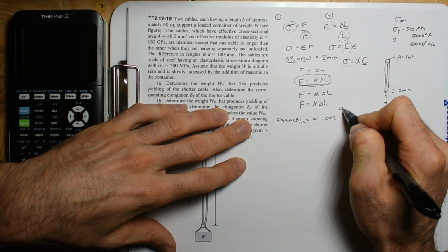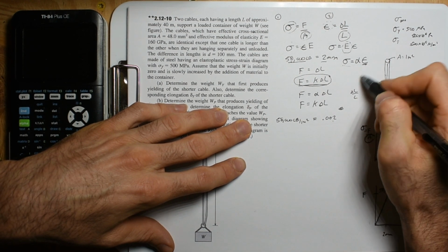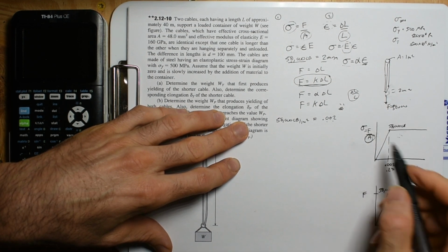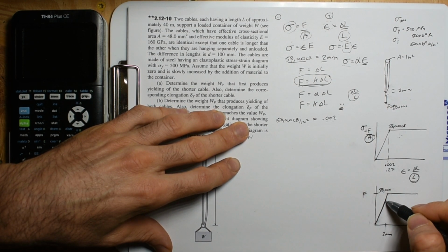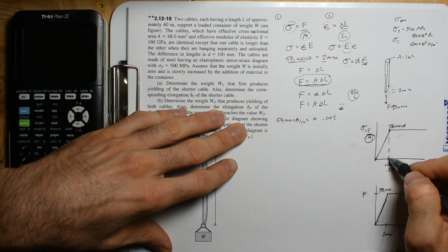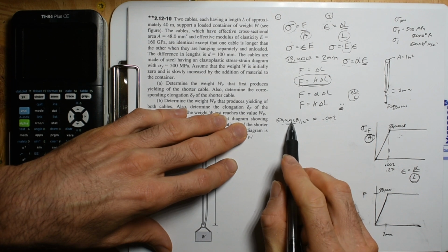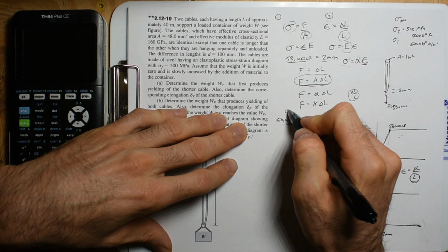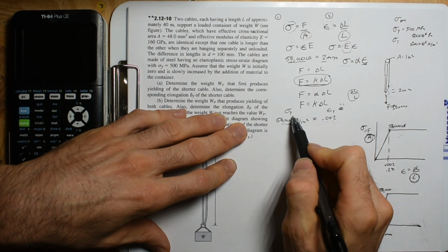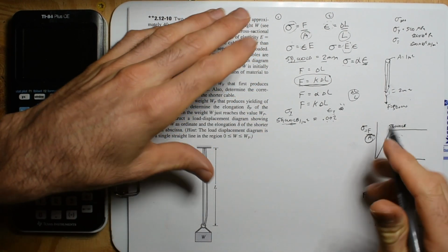0.002. So change in length divided by length, that's what strain is. If we observe 0.002, and that's what we're observing when we pull something in a machine, that's going to be synonymous with its yield stress. So we have yield stress, and I guess you would just call this yield strain, because you do have subscripts. I think that's useful.